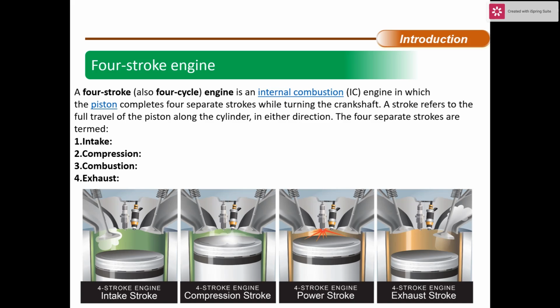Now, what happens in the intake stroke? It is also known as induction or suction. This stroke of the piston begins at top dead center and ends at bottom dead center. In this stroke, the intake valve must be in the open position while the piston pulls an air-fuel mixture into the cylinder by producing a partial vacuum in the cylinder through its downward motion.